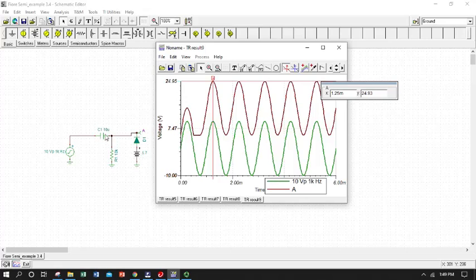So the capacitor wouldn't just charge to 10, it would charge to whatever point A is plus the peak, which is why I misspoke at the beginning with 24. And then that stays, has no way to discharge through the diode, doesn't have time to discharge through the resistor, and so we're adding signals all the way through.